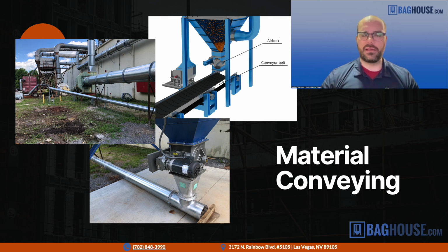Now, when you have pneumatic conveying, you're taking material and you're blowing it or pulling it through basically a small piece of ductwork. We usually call it piping to another space. So in these systems, like we said with filling the silos, for example, you might blow material from your truck that comes with material to deliver, blowing it up into the silo. That's pneumatic conveying. Or you might, from the silo, have it go down and load the truck or a barge or a train car. In that case, you're also doing pneumatic conveying.